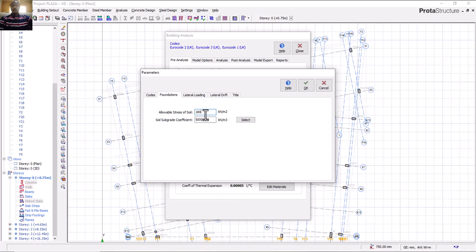So that if they see it, they know that they must carry out that particular test, because at the time you are designing this, they might not provide it. They might tell you to just use some bearing capacity from the architect, or I'm saying this from experience. Is that okay? Because whether you like it or not, it's not everybody within Africa that does a soil test. There are some structures where they will just ask you to do this, just do that. But for your own safety, you put that note there that this is what you used, and they must ensure they do it.